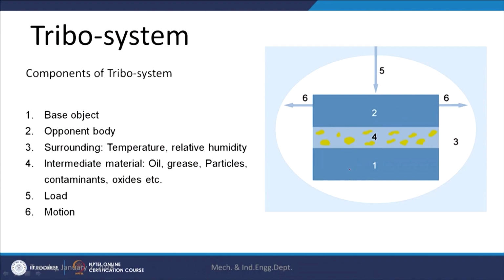Now, we will go through another type of wear, that is abrasive wear, which we can understand from this tribological system, as I talked about yesterday, the Tribo-system. Here this is component 1 which is under consideration, and it is in contact with another mating component 2, and between the two components some kind of separating film, in the form of oxides or lubrication or steam or something else, is present.